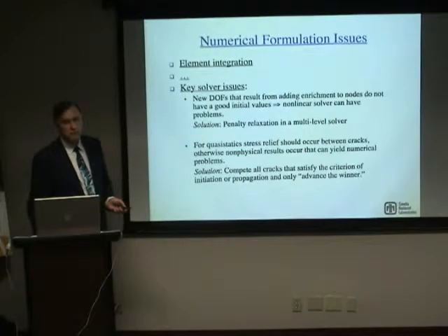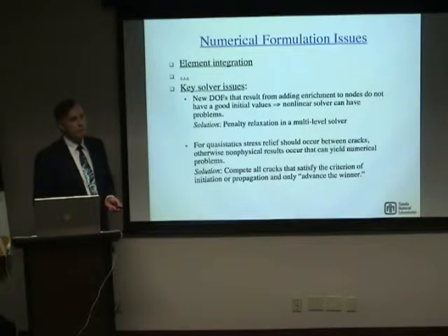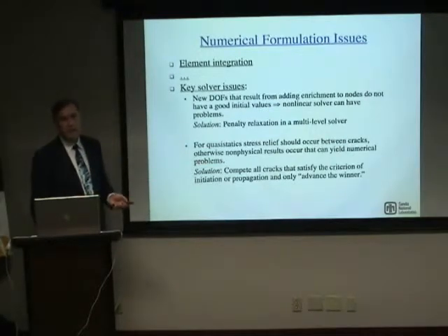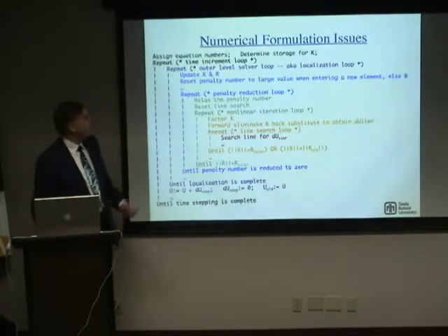So now we're talking about crack initiation as opposed to propagation? Yes. Right? So typically in the context of a cohesive crack formulation, it doesn't have to be this way, but we're going to use the same criterion in what I'm showing you for both. And if you didn't have the same criterion for both, then yes, you do have the issue as to how to weigh one versus the other in terms of satisfaction or not satisfaction of it. But in this case, for example, the problems I'll show today, it will be when your maximum principal stress exceeds the tensile strength or a fraction thereof.